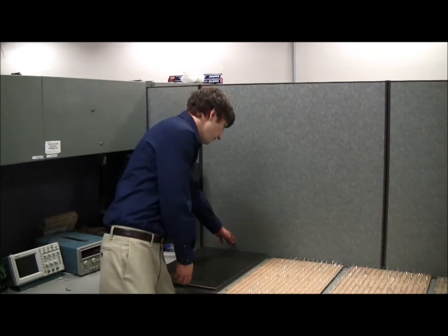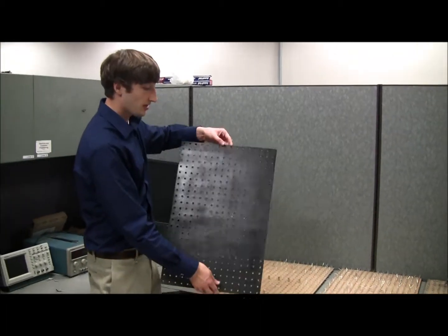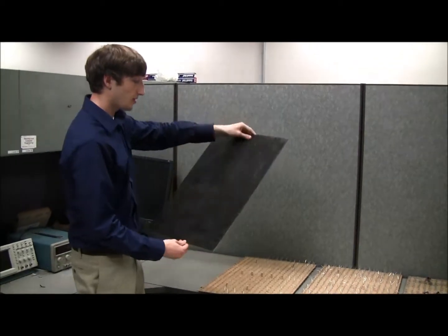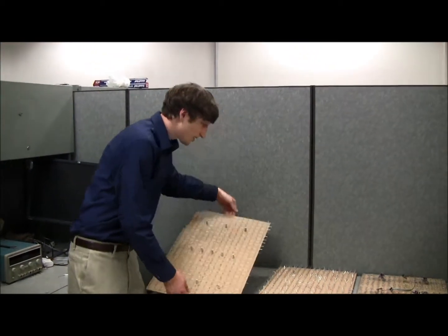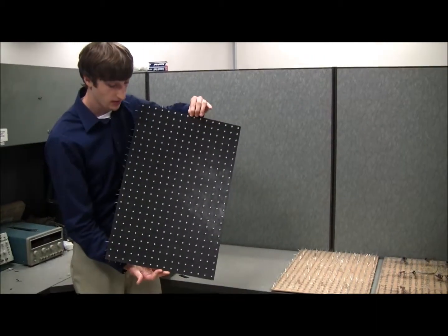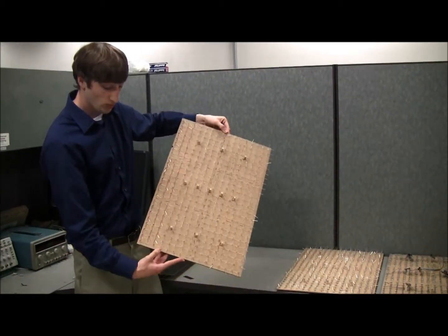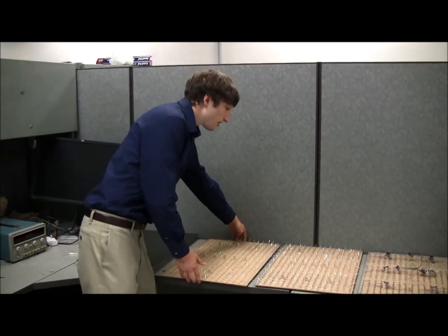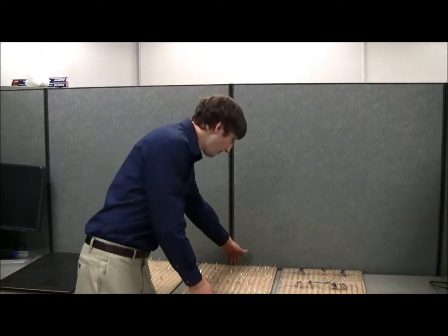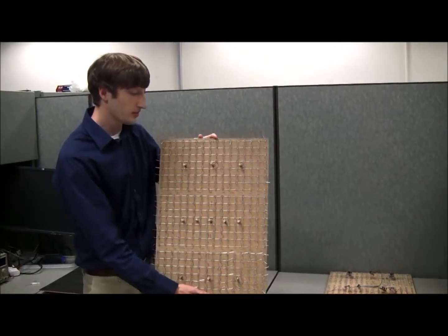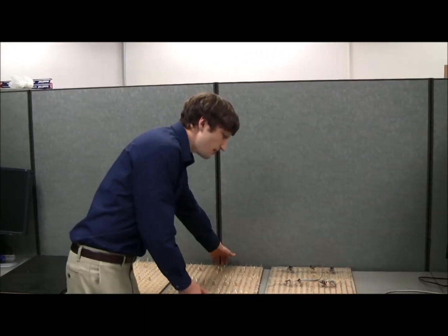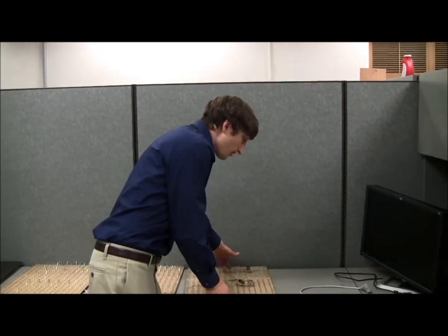Here I'll show a little bit about the making of the different panels to make up the display. First we start with a section of the panels. It's got 0 LEDs in it. Next stage is to put all of the LEDs in, connecting the anodes. Here we see all the LEDs are in, beginning to be wired up here. Next panel, everything has been wired up, connecting all of the different cathodes together, as well as all the anodes. After that's been completed, we move on and attach the different PCBs.